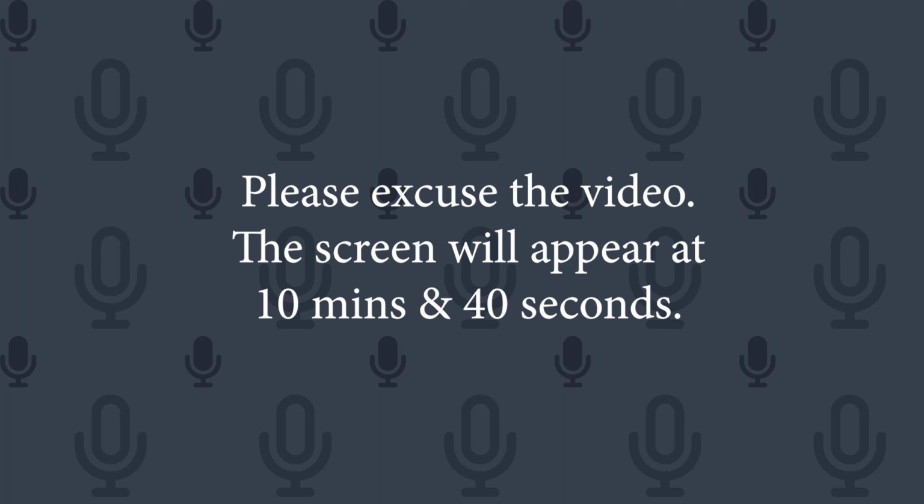So let's start with the PFA process and see how it helps you calculate the natural frequencies. Step one, you have to turn on the pulsation frequency analysis module. Step two, strike or ring the system. Step three, calculate acoustical frequencies and select the frequencies and pump RPMs of interest. Step four, create a PFA specific scenario representing the PD pump.